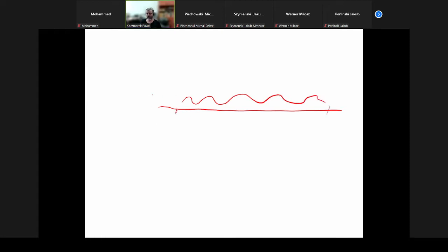So it means from the beginning of this grating, shorter waves will be reflected, and longer waves will be reflected from the farther part of this Bragg grating. So properly designing such a structure will allow us to create, in fact, every dispersion profile we want to have.